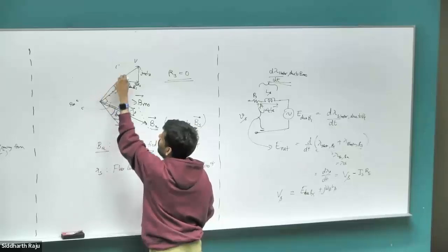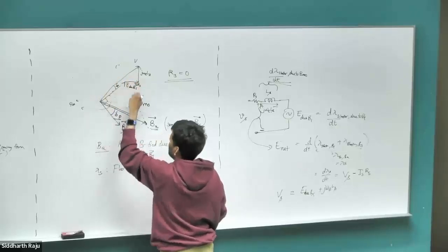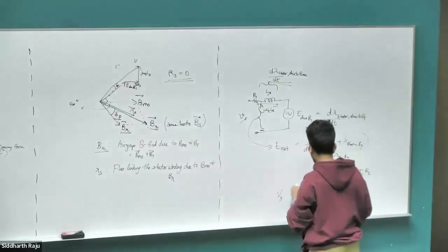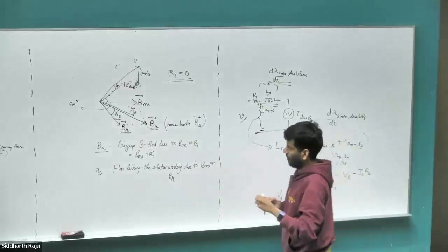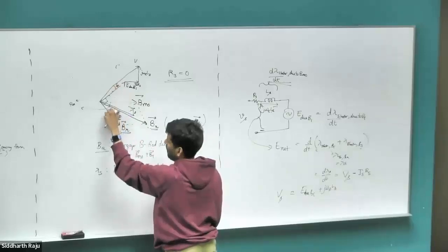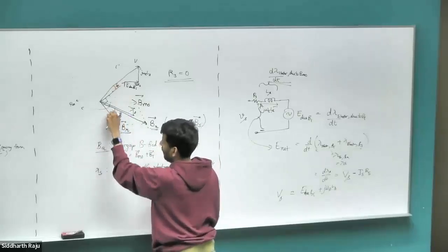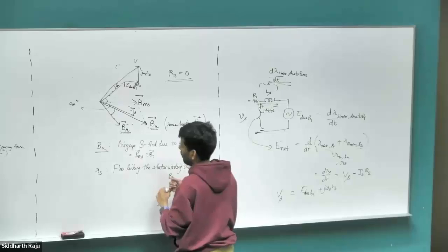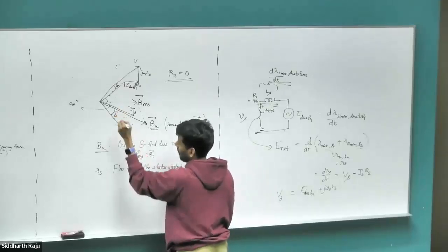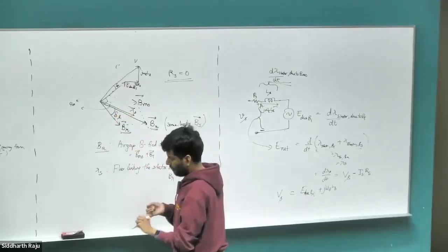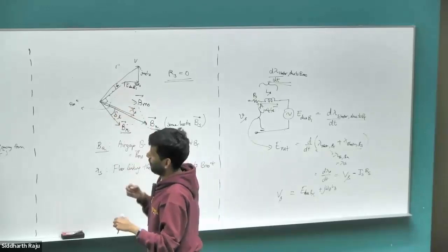The angle between the Vs minus Is Rs space vector, if you subtract that out, then that space vector would be at 90 degrees from lambda s. So this angle will still be delta P because that's a power equation, but this angle is no longer delta P, right? You can just call it some other delta. Let's call it delta L. But this angle would start to deviate from that particular angle.